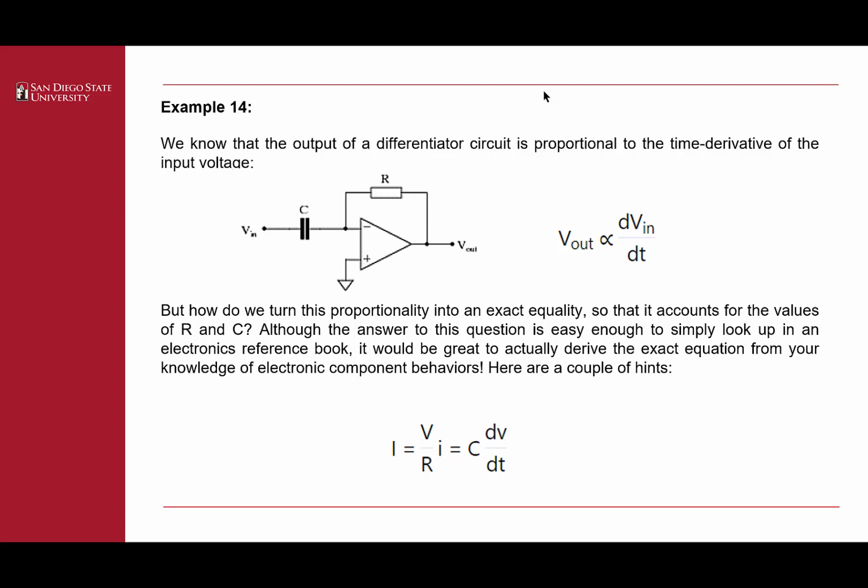But I here is also time varying, and this is why we should make a substitution over I. For this capital I, we should use the time varying version of the current, and the equation should become V equals R times lowercase i, which will be V equals R times C times dV/dt.